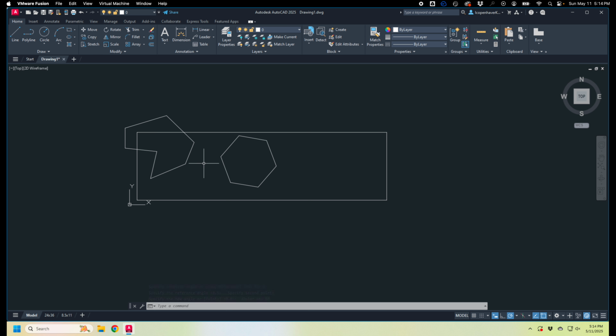Lovely. Okay. So let's say that I also have something like this, but I want to duplicate it and mirror it. Well, let's just talk about mirroring. I can start that command by clicking mirror, or I can type MIR, short for mirror, hit spacebar, and duplicate it. So let's go back and talk through that a little bit more closely.